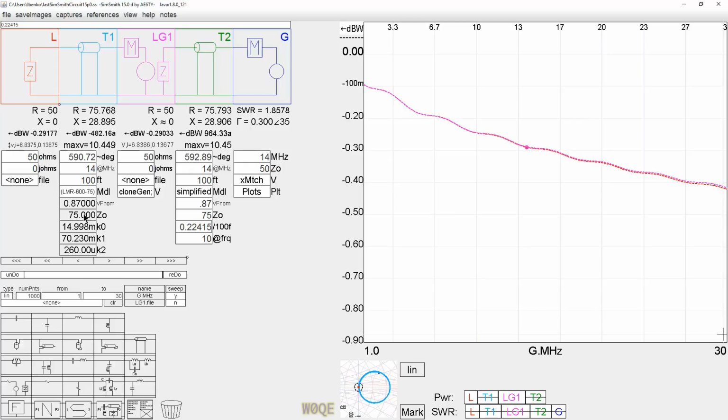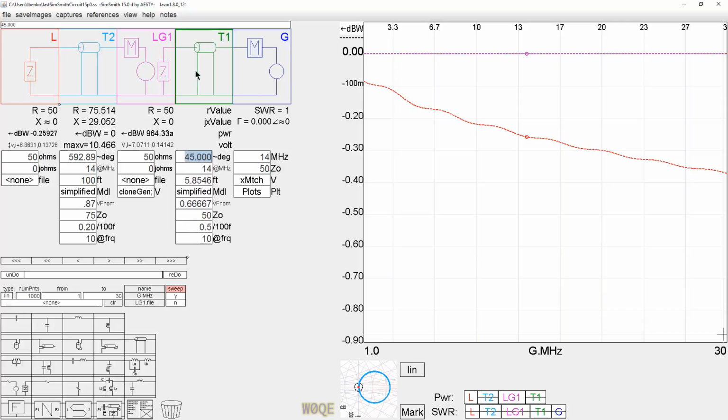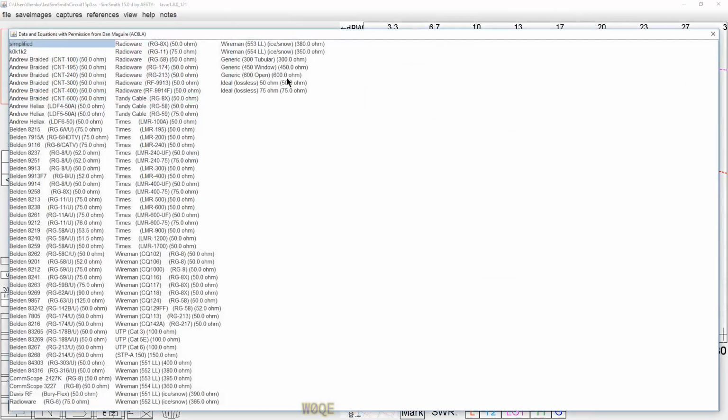Well, if 0.224 dB per 100 feet is what 0.6 inch diameter coax can give us, 0.875 inch coax is obviously less than that. So I'm just going to define this at the moment and call it 0.2. It might actually be less than 0.2, but I don't know. Let's call it 0.2. So we're going to dispose of this piece, and we're going to call this our free coax that we got. Now we're going to compare it to something that we're going to purchase.